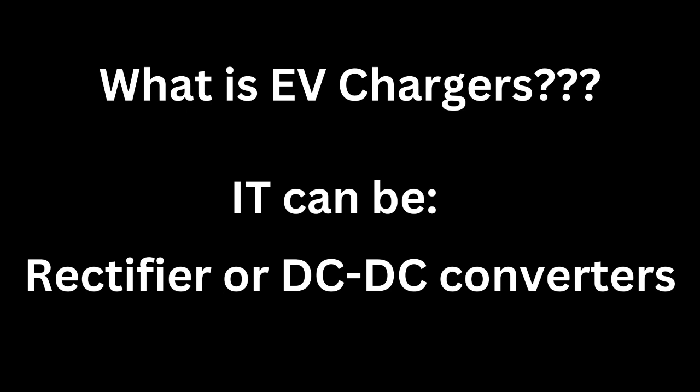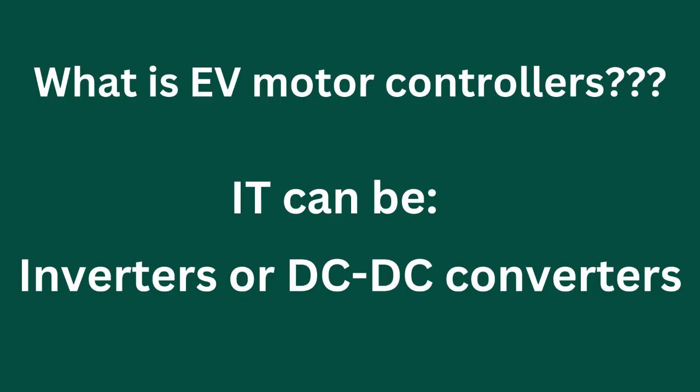Now the question comes: what type of power converter is an EV charger? It can be a rectifier or DC to DC converter. What type of power converter is an EV motor controller? Depending on the type of motor, it can be an inverter or DC to DC converter.